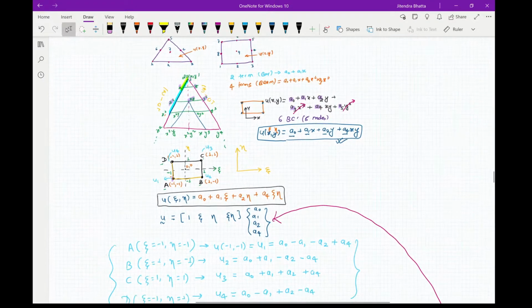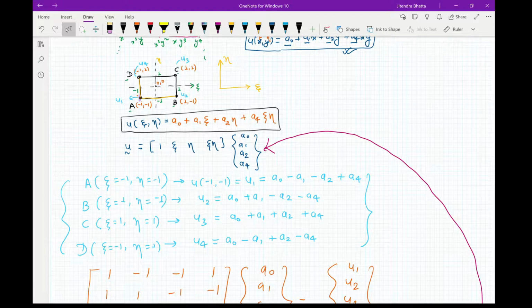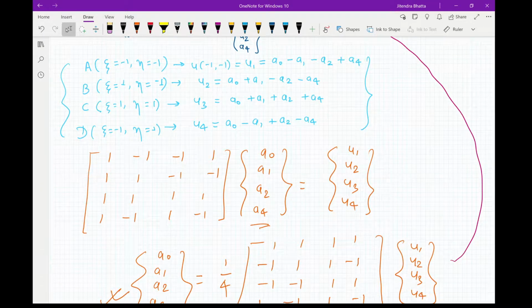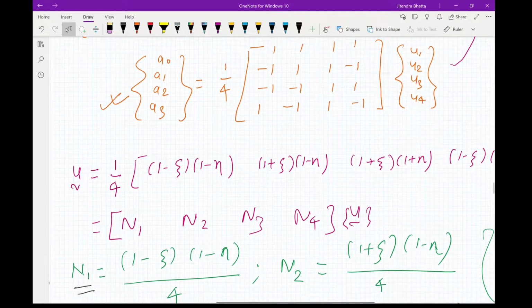and we obtained the shape functions using the standard procedure of assuming a shape function and then using the boundary conditions or the constraints at each node for the shape functions to obtain 4 equations and solving them uniquely using the matrices.